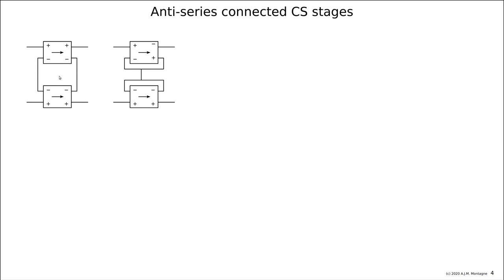And if they are exactly the same, we might as well do this, because then there is no voltage difference between the two minus inputs and the two minus outputs, because the elements are exactly the same. And then placing the MOS in it would just result in a differential pair as we would have it. You can also put two vacuum tubes in it, or two biased NPN or PNP bipolar transistors. Any three-terminal element will do.